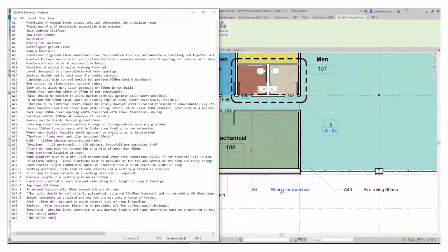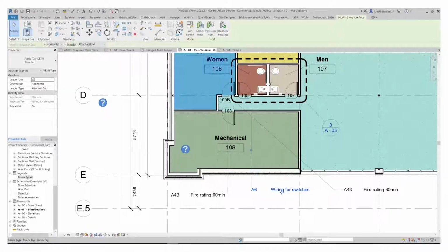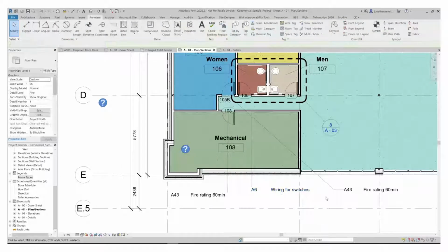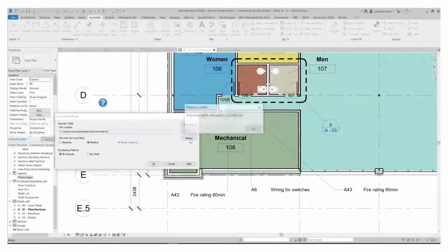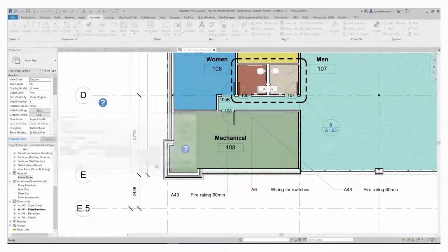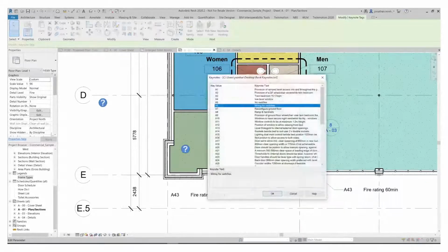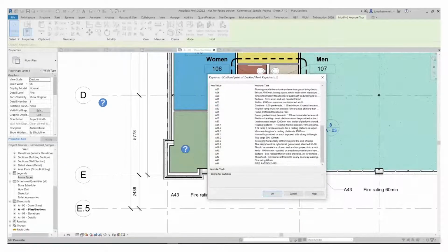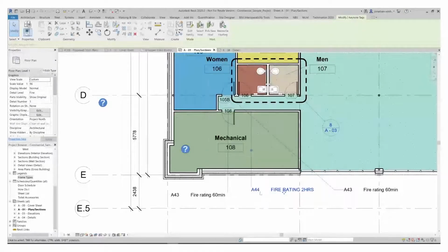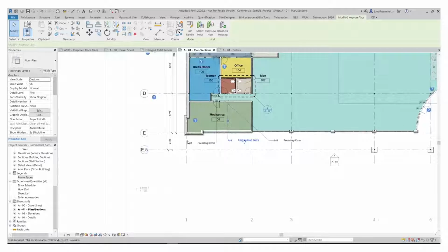Now I do need to reload, but obviously in an ideal situation you'll have all of your notation already created. But I'll show you how to reload this. Go into Keynote Settings, just hit reload for the same one. It's been successful. Click OK. Simply then go in, select your notes, say I want to change that note. You can see in my list I can select from my drop-down list, click OK. That note has now been loaded in, and I can see it's updated.